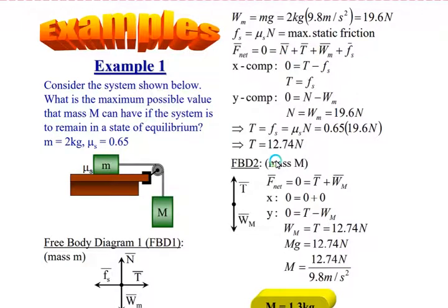So if we look, we have four forces for our first body of consideration that we need to consider. Number one, we have the normal force, we have the tensile force, we have the weight, and we have the force due to friction. So if we look at the horizontal component, the only ones here are your tensile force and your force due to friction. So we equate it to 0, we have T minus Fs is equal to 0. So we can get our value, which is T is equal to Fs or mu s N, so we need to get the value of our normal force.